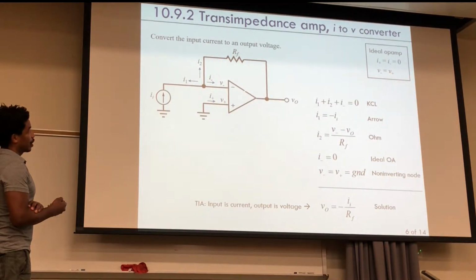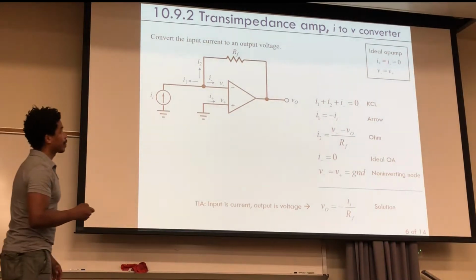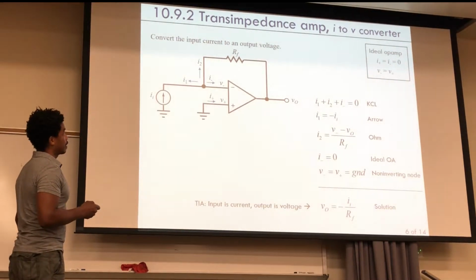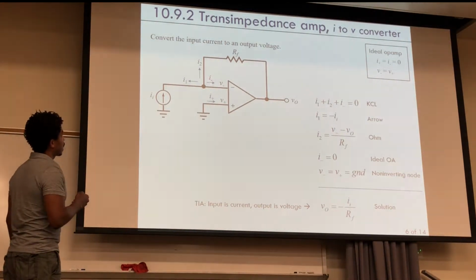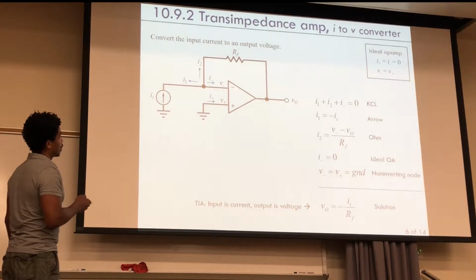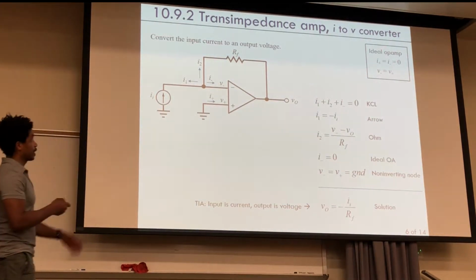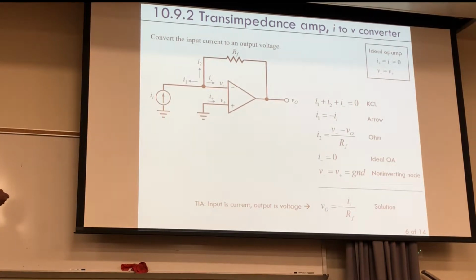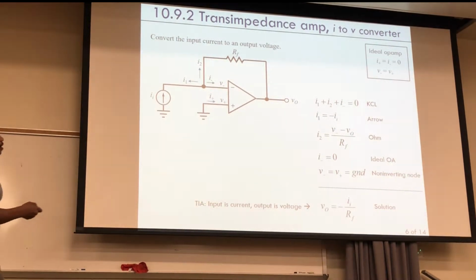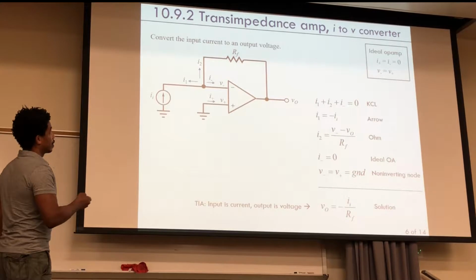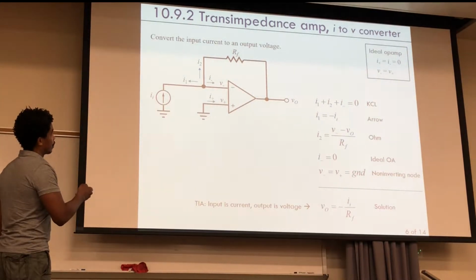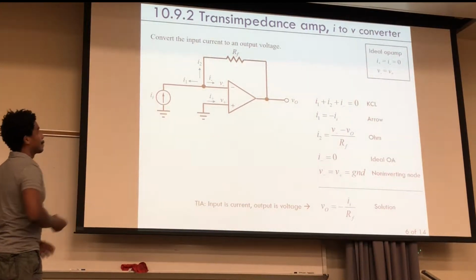you can look at this in most cases as an ideal op amp. If it's ideal, that means these currents, I negative and I plus, going into the non-inverting and inverting inputs, those are all 0. Okay, so if you're going to do KCL, you got to watch out for that. That's 0, and that's also 0. The voltages are equal. So the inverting and non-inverting, these are equal.